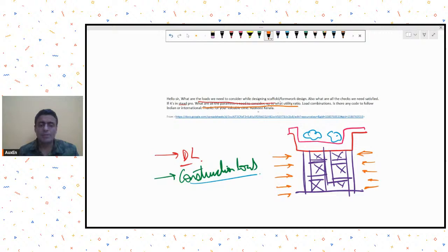So parameters, if you mean the design parameters, your general effective length parameters or your general lateral torsional buckling parameters may have to be used. What utility ratio? The utility ratio should be kept less than 1.